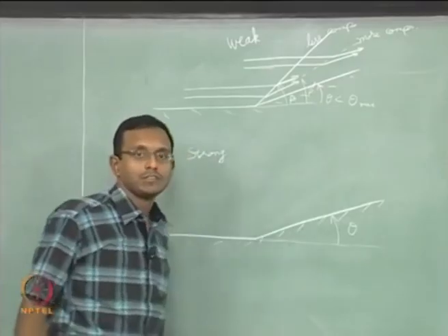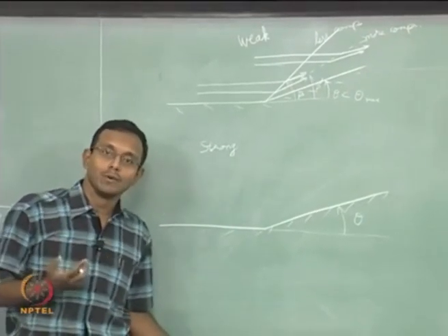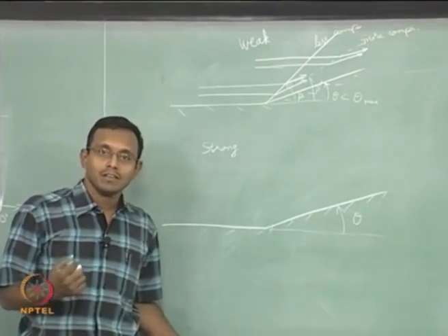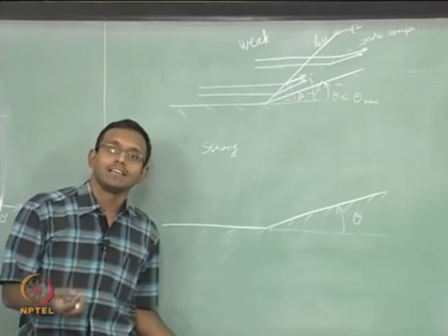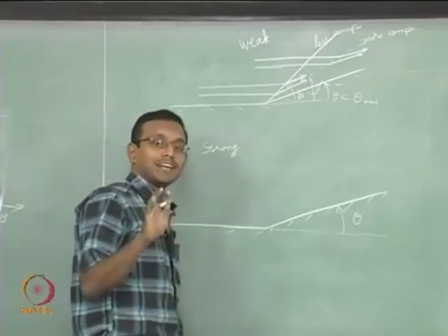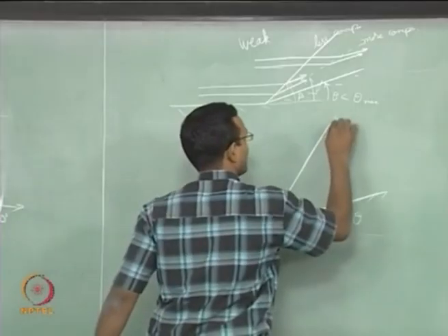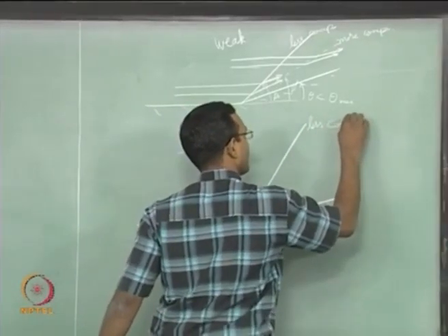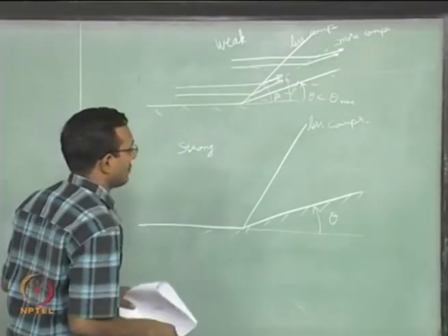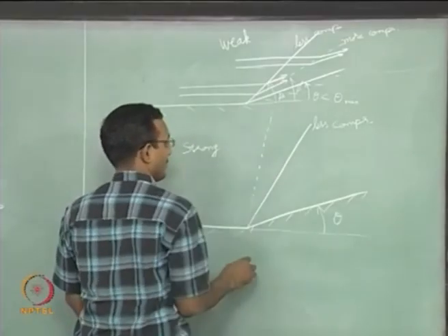In a strong solution, we already observed that the kinetic energy of the fluid is converted to pressure energy and temperature energy or enthalpy much higher than in the case of weak oblique shock. Okay. So, we are going to use that statement mainly. I am going to say this is my original less compressible situation, okay, and we already know the answer that it is going to be higher. We are supposed to explain that.